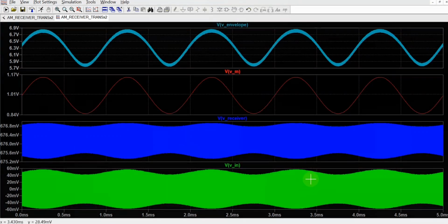This AM wave was passed into a circuit. This was received and amplified. After amplification of this signal, it was passed through two more such stages so that the envelope detector could function properly. Lastly, we see that the output of the envelope detector exactly follows the message signal, which means that the envelope detector retrieved the message signal from here. So the circuit works finely.